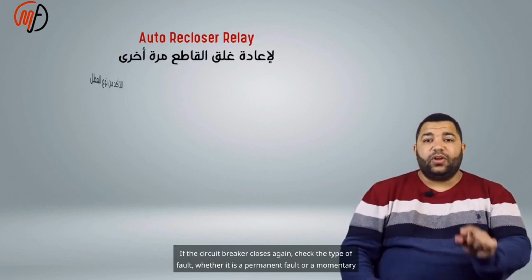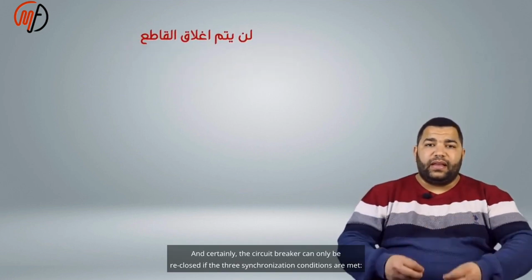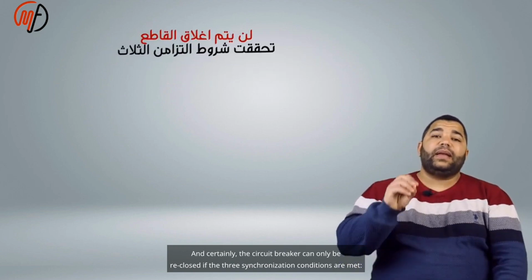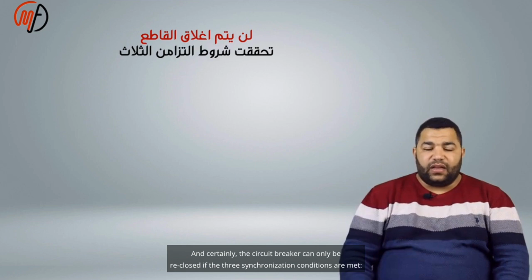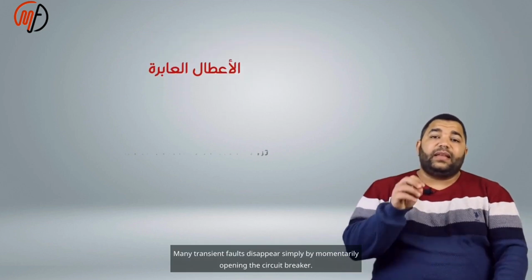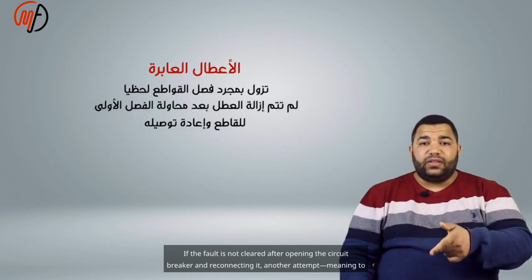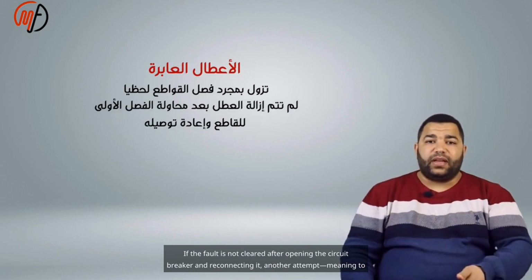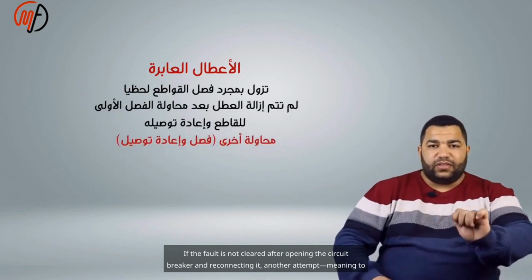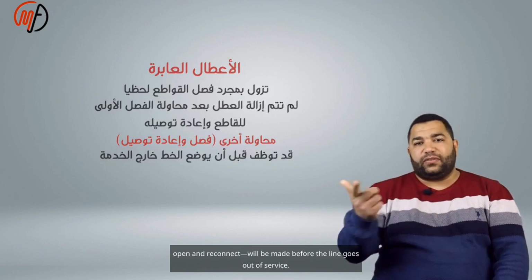If the circuit breaker closes again, check the type of fault, whether it is permanent or momentary. The circuit breaker can only be reclosed if the three synchronization conditions are met: voltage, phase, and frequency. Many transient faults disappear simply by momentarily opening the circuit breaker. If the fault is not cleared after opening the circuit breaker and reconnecting it, another attempt, meaning to open and reconnect, will be made before the line goes out of service.